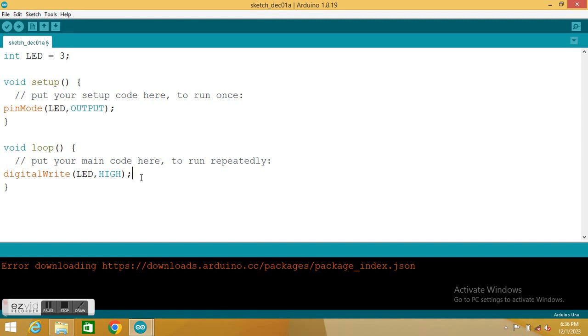and then execute what you've told it to do. Now maybe after the LED lighting, after some seconds, like maybe 2 seconds, I want it to go off. So that's how we bring in the keyword delay. I said 3 seconds, so why am I writing 3000 instead of 3? When programmers were coming up with this language, we are using C, they made it in a way that it does not read in seconds, but it reads in milliseconds, and we all know that 1 second is 1000 milliseconds. That's why I say 3000.